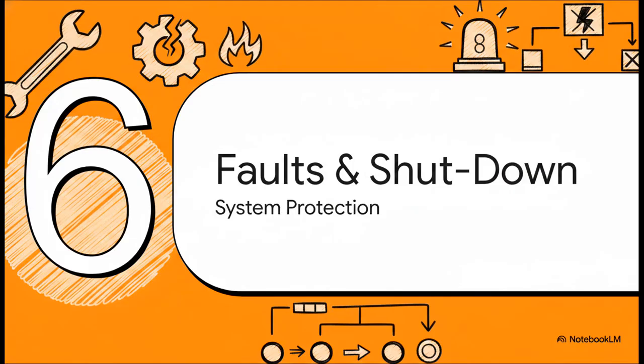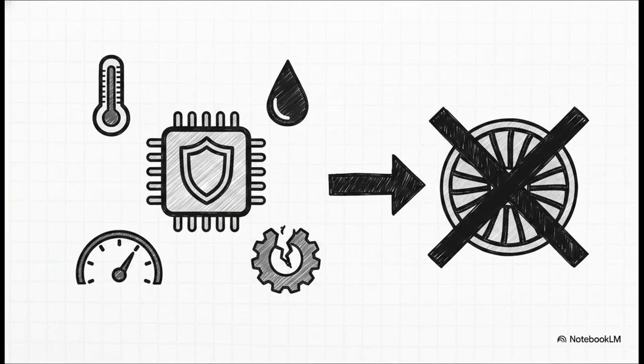Finally, Section 6, Faults and Normal Shutdown. As we've seen, the FADEC system is incredibly self-protecting. If it detects a fault, it isolates and shuts down the APU. And the monitoring is totally comprehensive. It looks for overspeed, underspeed, start failures, and acceleration failures. It watches for EGT overtemperature, low oil pressure, or high oil temperature. It even monitors for failed sensors, failed valves, relay issues, and internal failures.